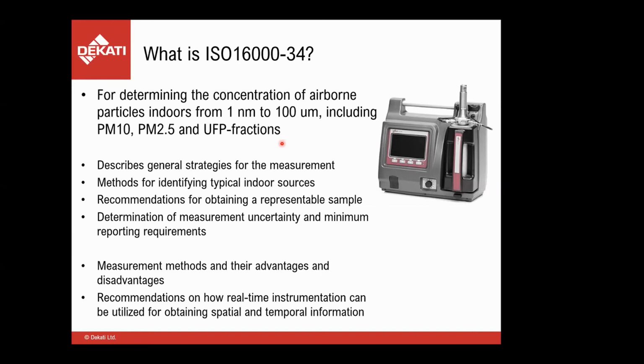It has recommendations for obtaining representative samples, how to determine measurement uncertainties, and what the minimum requirements are when you are doing indoor air quality measurements according to this standard. Quite a big part of the standard itself discusses different measurement methods and their advantages and disadvantages. And as said before, it gives recommendations on how the real-time data can be used to get spatial and temporal information.